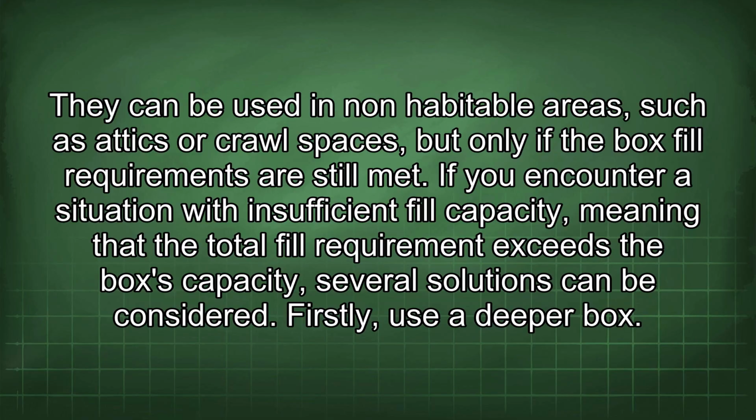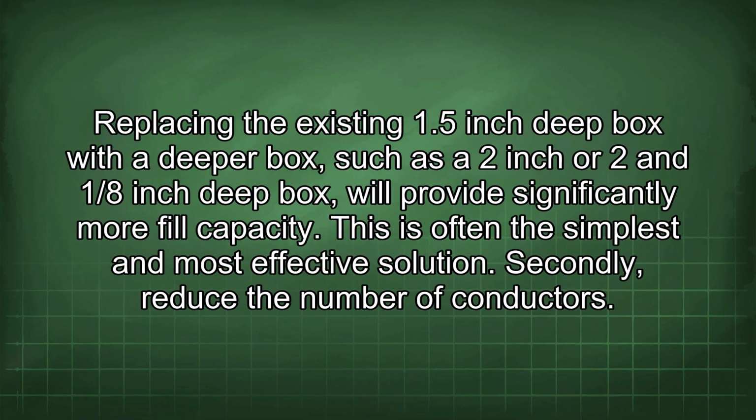If you encounter a situation with insufficient fill capacity, meaning that the total fill requirement exceeds the box's capacity, several solutions can be considered. Firstly, use a deeper box. Replacing the existing 1.5-inch deep box with a deeper box, such as a 2-inch or 2 and 1/8-inch deep box, will provide significantly more fill capacity. This is often the simplest and most effective solution.